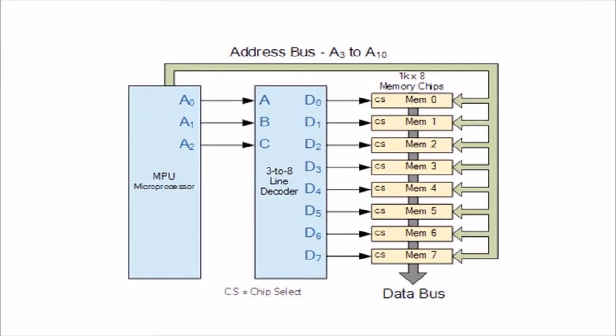The binary decoder requires only 3 address lines A0, A1 and A2 to select each one of the 8 chips, while the remaining 8 address lines select the correct memory location on the chip. Having selected a memory location using the address bus, the information at the particular internal memory location is sent to the common data bus for use by the microprocessor. This is of course a simple example, but the principle remains the same for all types of memory chips or memory modules.